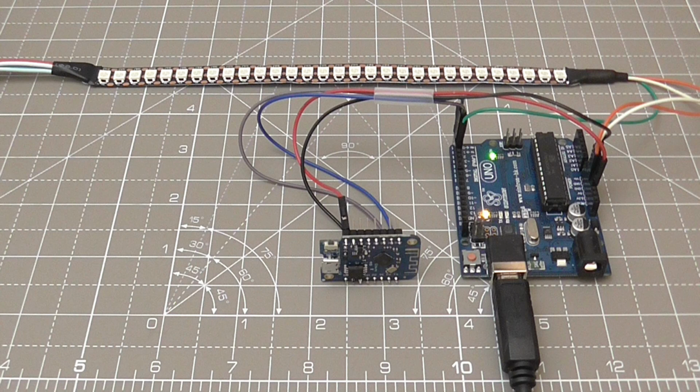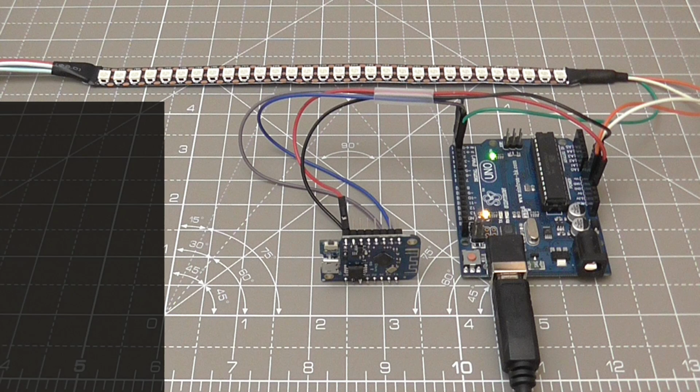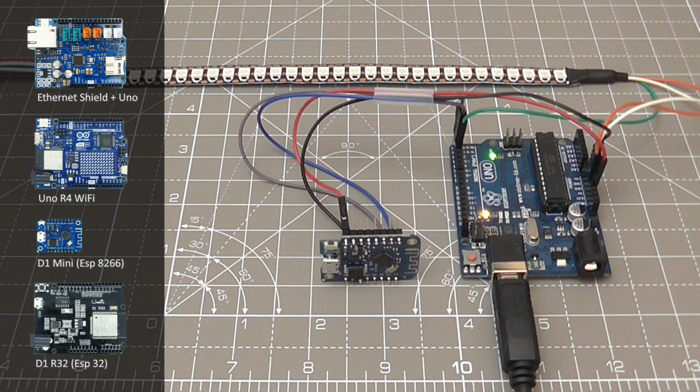To build the LED Effects Web UI project, you will need a network-enabled Arduino or compatible. You'll also need an Uno R3 connected to an addressable RGB LED strip. When in operation, the two boards will need to be connected to each other using their serial pins, but kept disconnected when uploading the source code.